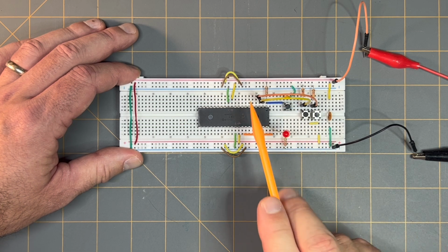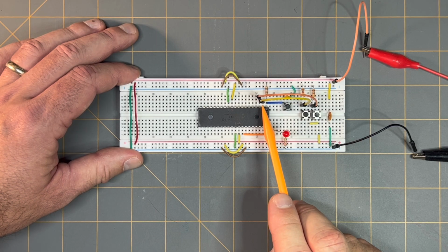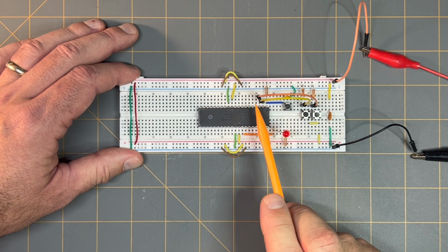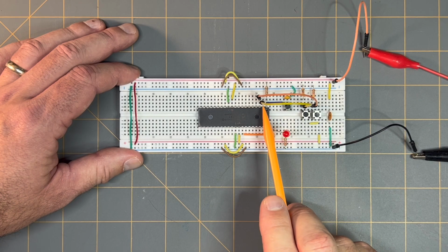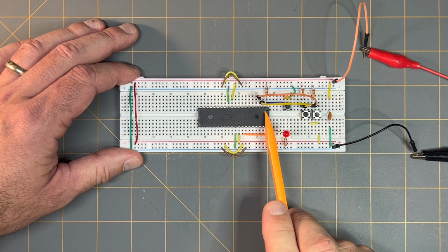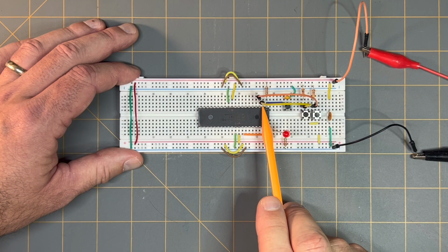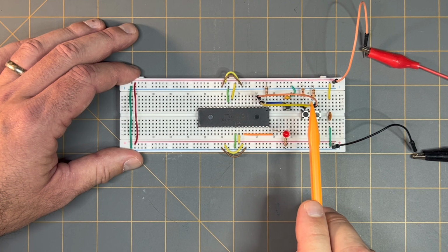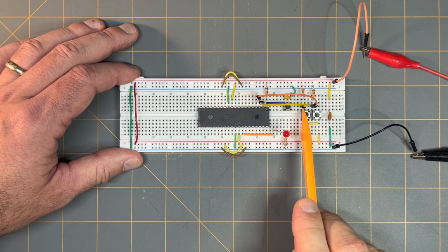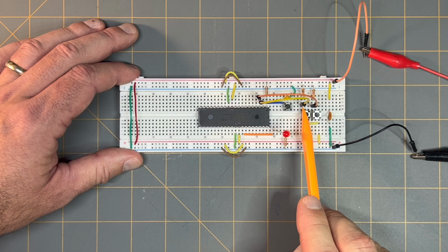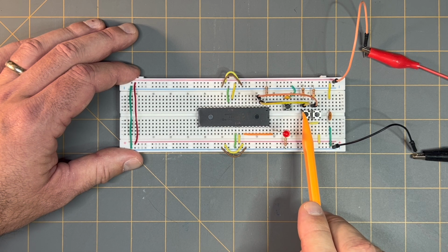Next, moving on to the connections coming from the PIC to the switches. For switch 1, I took this yellow jumper wire here, and I connected it to a point in line with pin 2. That's at point C23, and the other end of that yellow jumper wire goes to a point D12, and that point is in line with one of the legs of switch 1, and that was the leg at point E12.